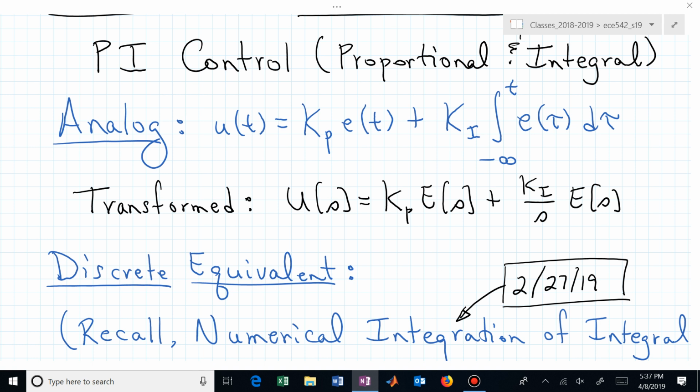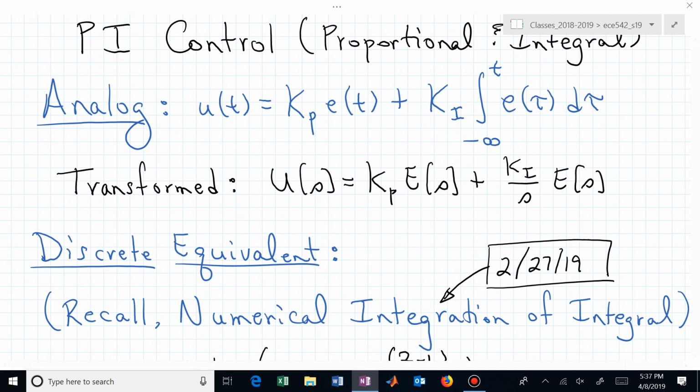We can factor that out, and what we want to do is actually find this PI controller in a discrete setting. What's the transfer function associated with a PI controller? What's the transfer function of a P controller? That's just K. That's an easy transfer function. What we want to do now is try to find the transfer function associated with a PI controller.